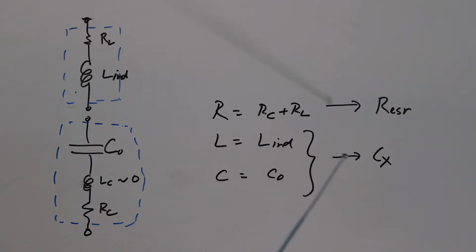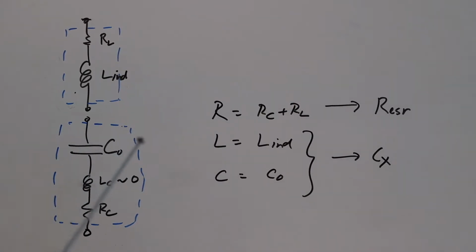And if the measurement shows that it's actually increasing in the value of Cx, it proves that the inductor actually degrades the performance of the capacitor, mostly in terms of the dissipation and the quality factor, but effectively changes the capacitance that is measured, although I'm not quite sure if that is the real effect in the system.